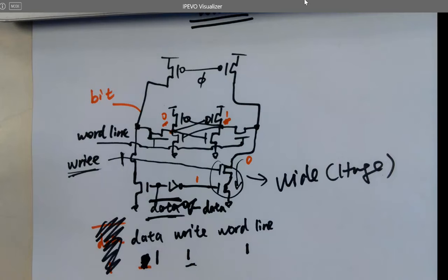But when you are driving bigger circuits with a lot of capacitance, we analyze all the capacitance of the digital nodes. Remember the Miller effect, you have all the caps around the gates. When you have huge transistors to be driven, you need huge gates to drive them as well, because you need a lot of current. You need a super wide channel connected to the ground and also to VDD, so you can dump a lot of charge and also discharge it, drain it to the ground.